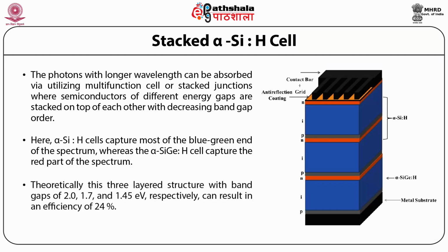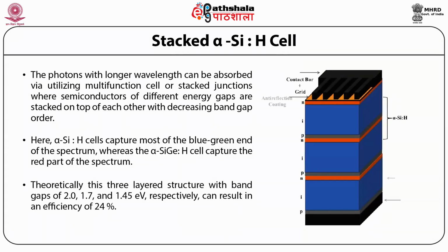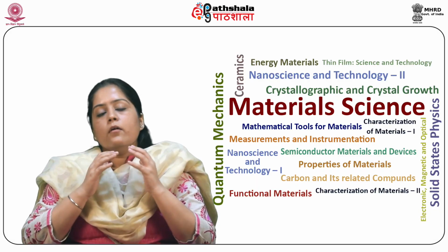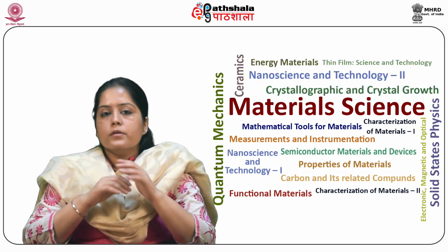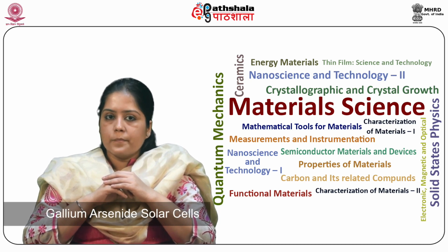Theoretically, this three-layered structure with band gaps of 2, 1.7 and 1.45 electron volts respectively can result in an efficiency of around 24%.